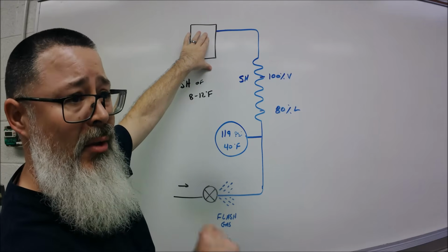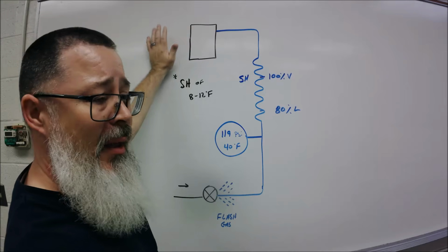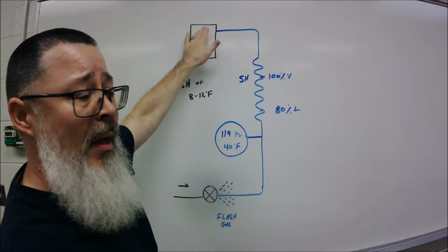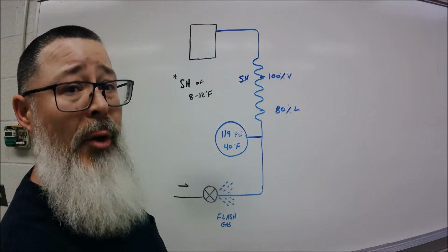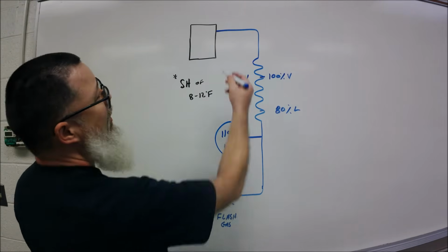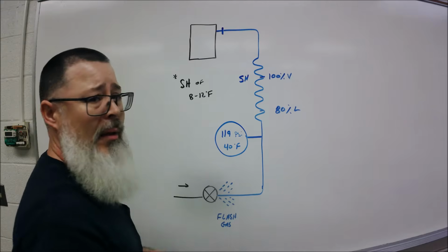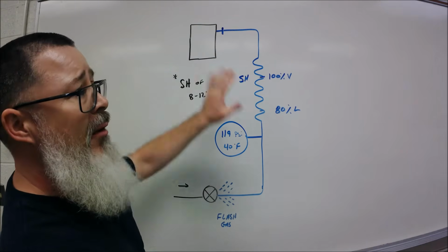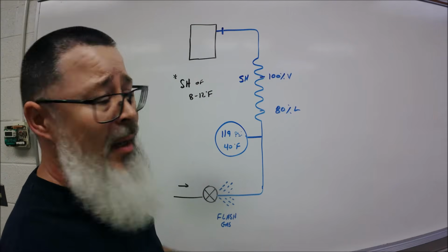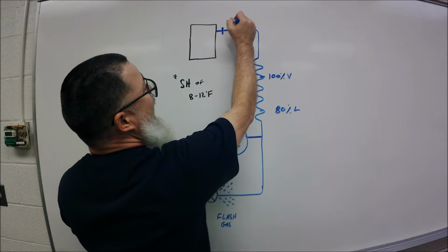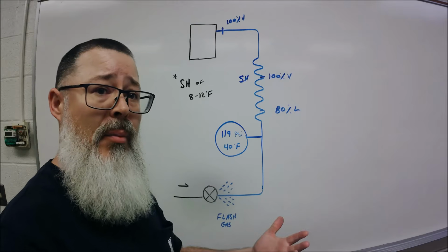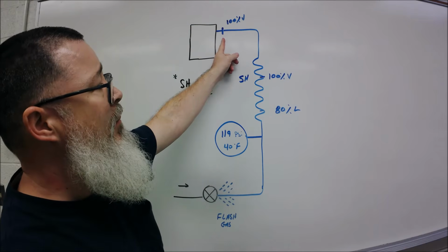So for the low side of the system, for the evaporator superheat, not mentioning anything about compressor superheat, but for the evaporator side, we know it ends at the compressor. So if I were to say have 1 degree of superheat, what does that mean, all right? How do I think about that? Well, I like to put a little mark, like I said, since we have just a 2D kind of version of this, I like to put a mark right there. So if I said I had 1 degree of superheat, then that would mean that I did get 100% vapor. I'm not going to slug the compressor with liquid,